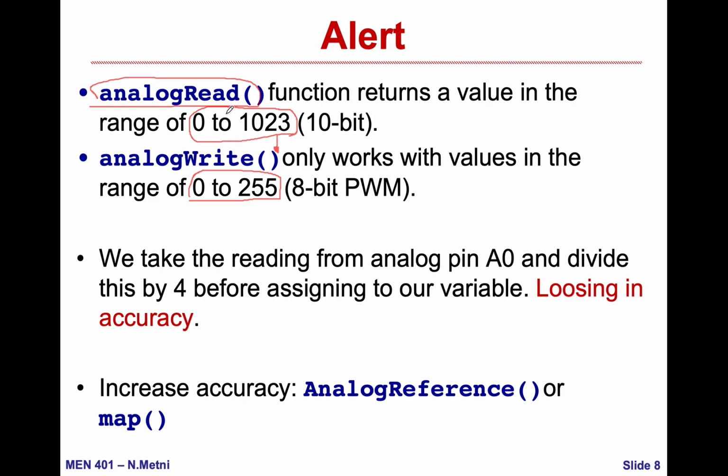Okay, so what can I do in this case? Here I want to go into the resolution. The resolution of the A to D converter is equal to V high minus V low over 2 to the power k minus 1.